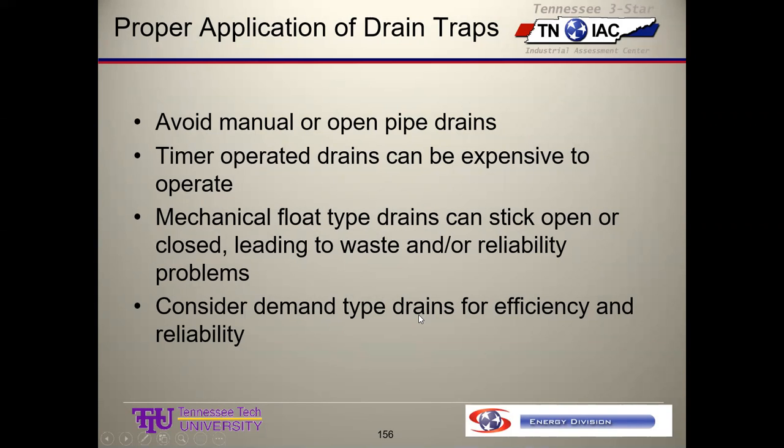And you always set the timer to be open more than it needs to make sure that you don't back up any moisture in the system. So if it needs to be open once an hour for 5 seconds, it's probably open 3 times an hour for 15 seconds. That's the way the world works.